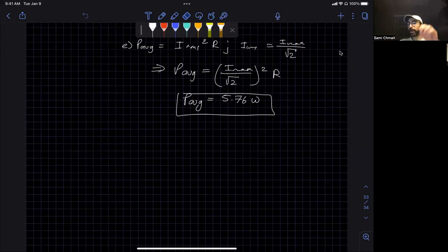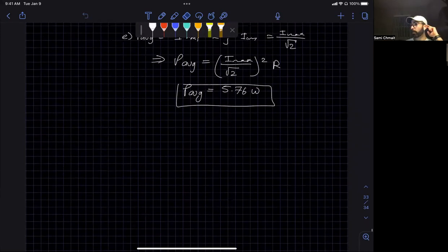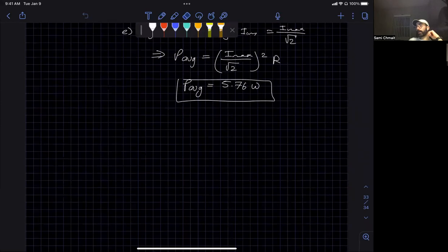Okay, so here we have a situation where we have 80 kilowatts of power to a town through transmission lines. We know the resistance through the lines. We want to determine how much the power is saved if we use a step up and then a step down. And that's transmitting the power at 120 volts. And we assume that each transformer is 99% efficient. So we need to make that modification on each one.